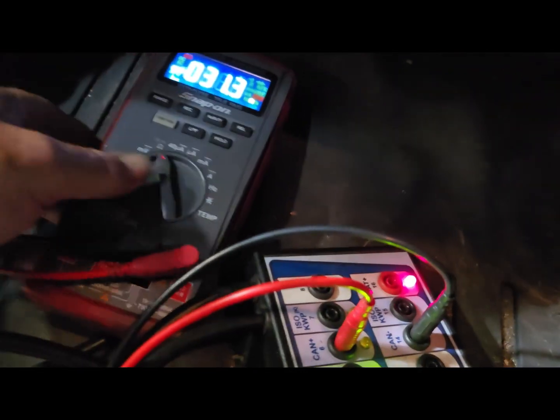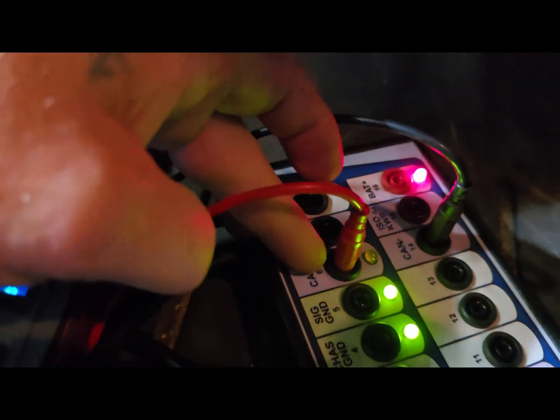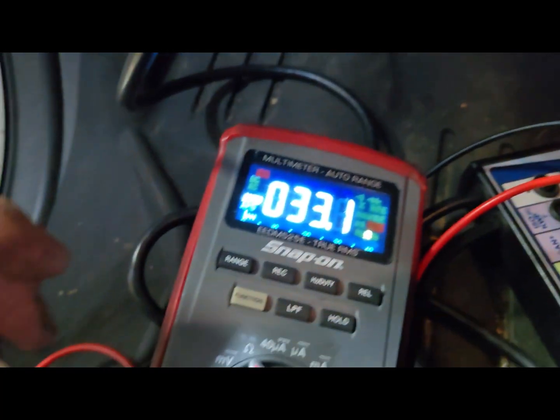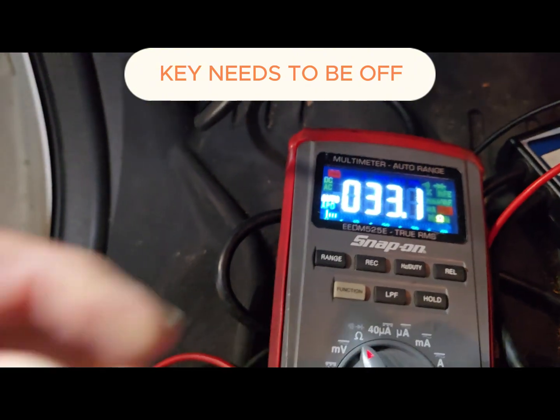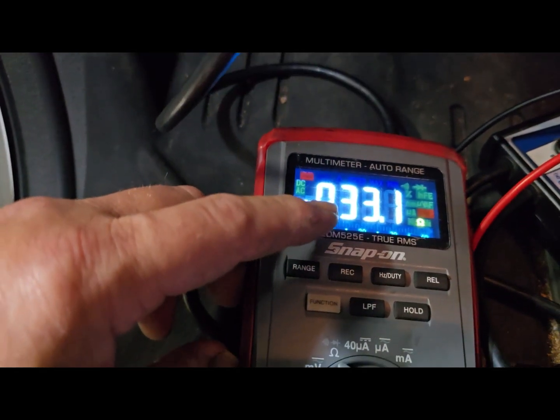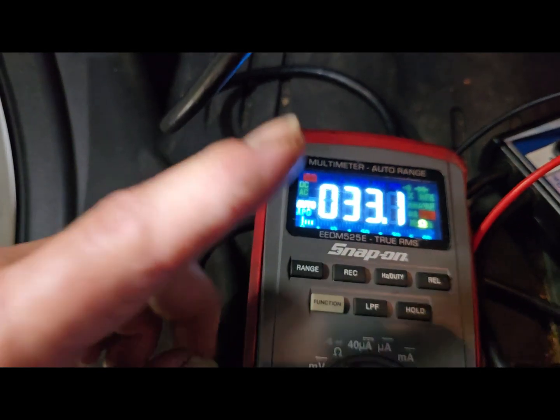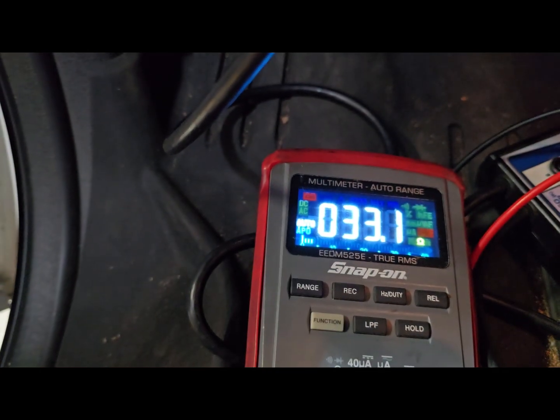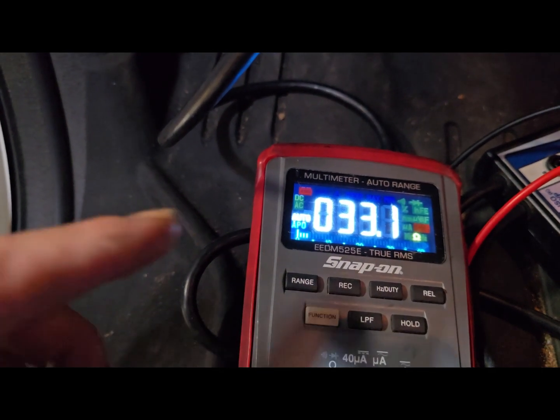The first thing you're going to do is hook up to pin 6 and 14. This is CAN high and CAN low, and you're going to look at your ohms reading. You should have 60 ohms. Now, I've got a whole bunch of stuff disconnected on this CAN system, and I only have 33 ohms. So we definitely have a problem here.